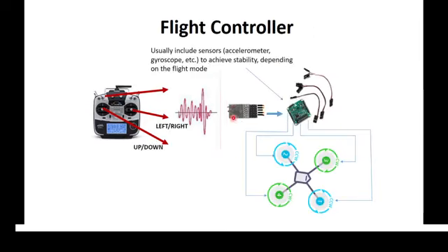In a drone system, motors and servos are not controlled directly by the receiver as explained before. It would be impossible to operate the drone from the radio in such a way. A drone system has a flight controller that generates the required signals to control the motors, to implement the basic movements such as elevate, go forward, or turn right.